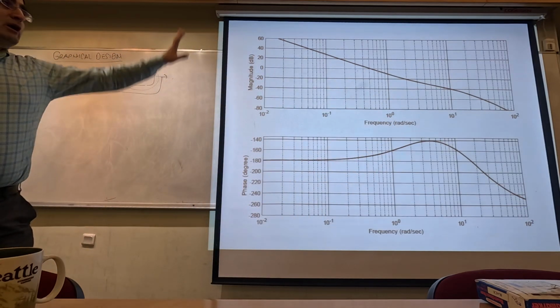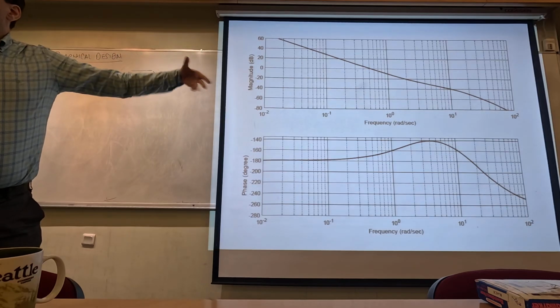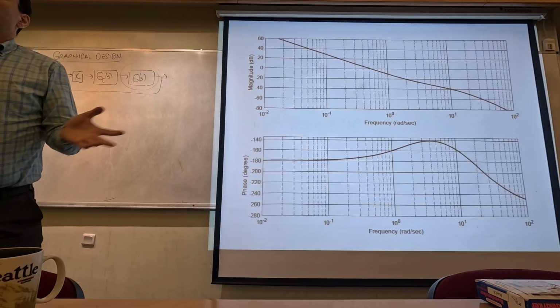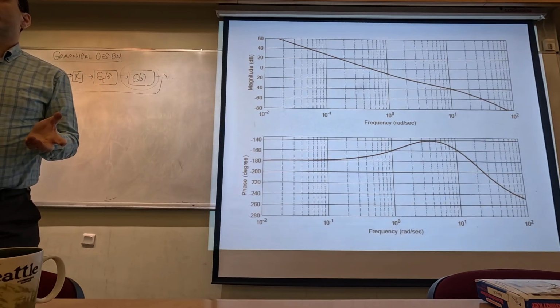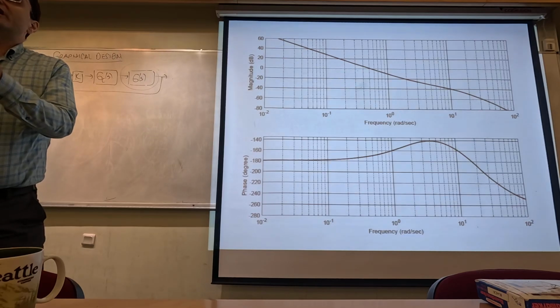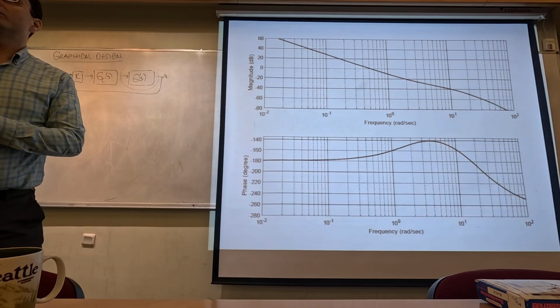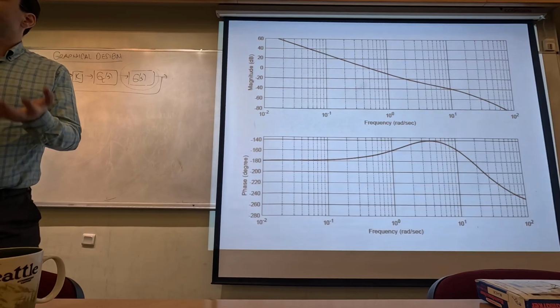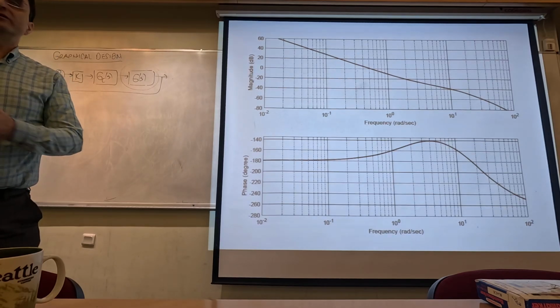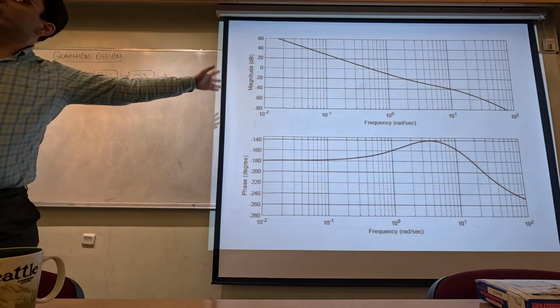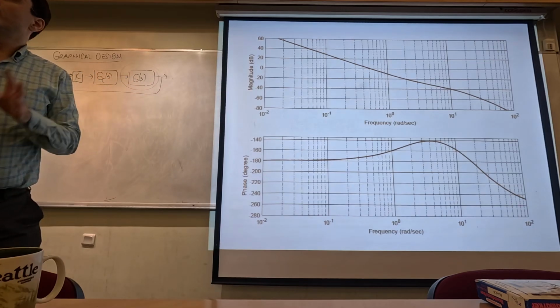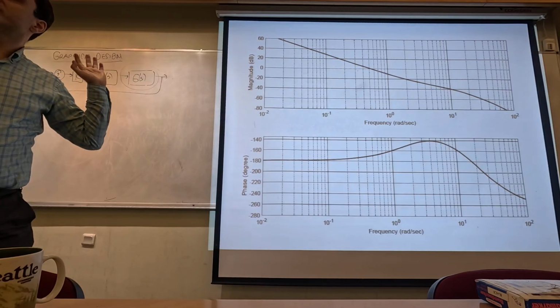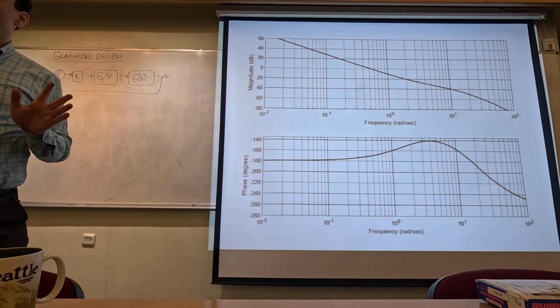And when you obtain such a Bode plot, why do we do that? Because we don't know the transfer function of the system that we would like to control. When we don't know the transfer function, either we have to do something to obtain it, or we can obtain a Bode plot instead, and work out our controller design without knowing the transfer function at all.